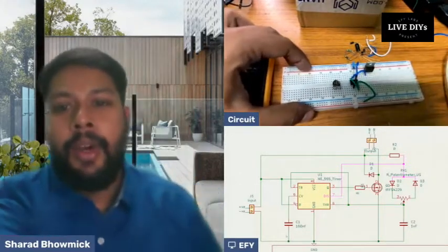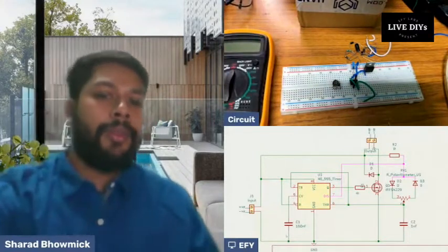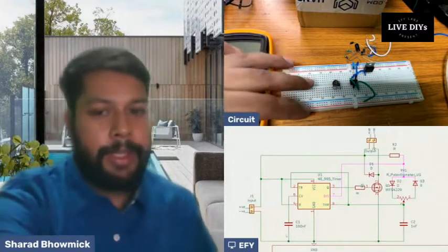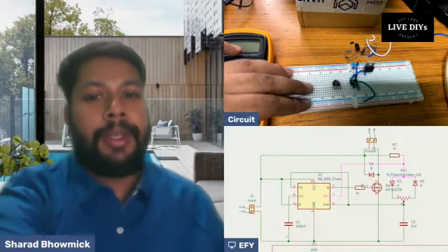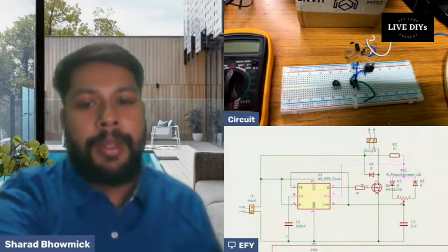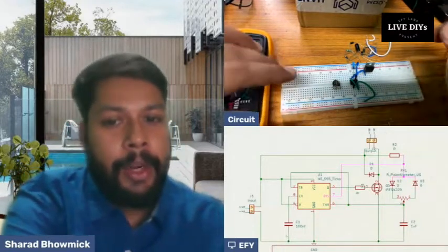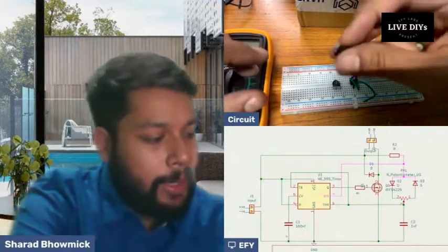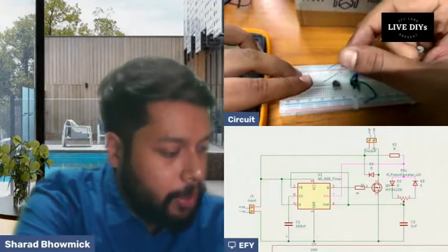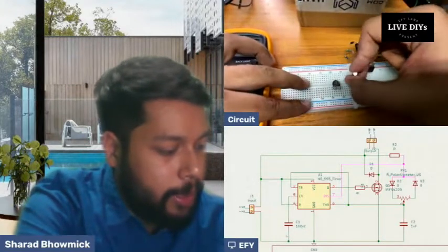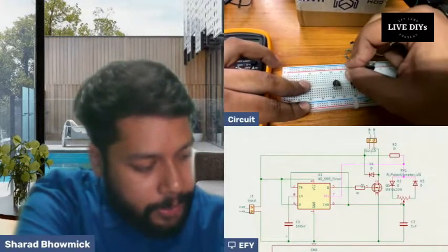Right. Now, pin 5, we just need it for filtering. So we are using pin 5 just for filtration and making the system more stable. A 100 nanofarad capacitor works fine for this. So we'll have to connect the ground with pin 5. Make sure that the negative terminal, or the smaller terminal, is connected to the ground, whereas the longer terminal is connected to your 555 IC's fifth pin. So we've done that.